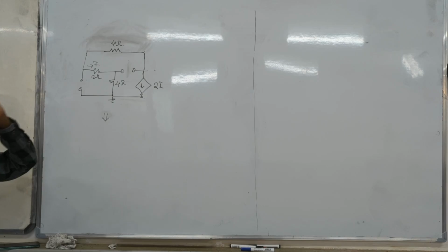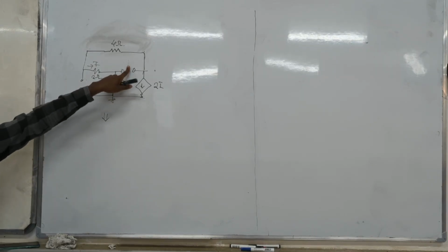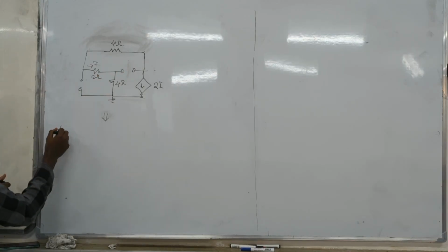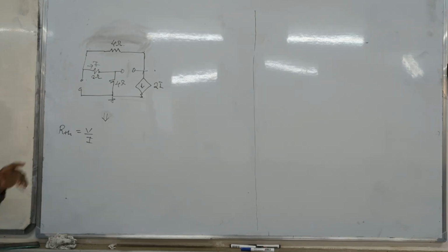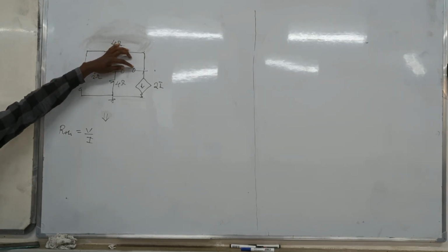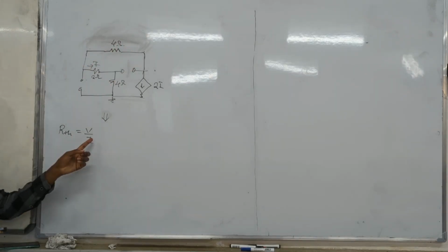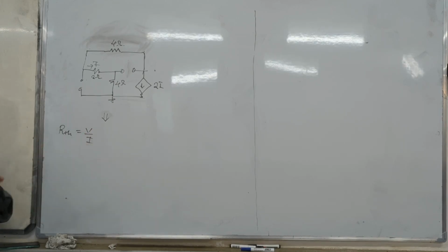Because the process, the Thevenin's steps, when you follow them, the last part for you to get the resistance, what we actually do, even in a circuit which has only dependent sources, is you put a voltage here, a test voltage. Because what is resistance? Voltage over current. So what we are doing is we'll set a voltage, let's say 1 volt or 1 amp. Then you find, using the circuit, if I set voltage, I'll get current. If I set current, I'll get voltage. Then divide the two.